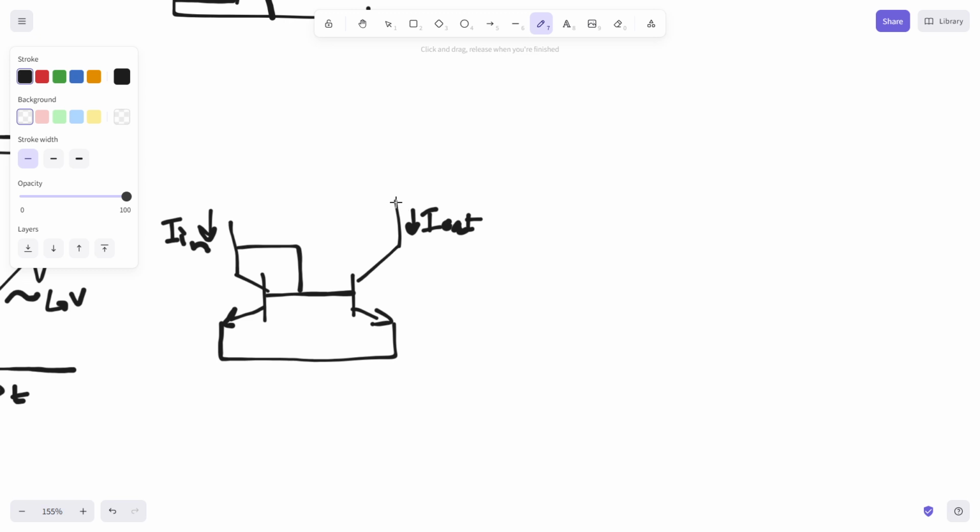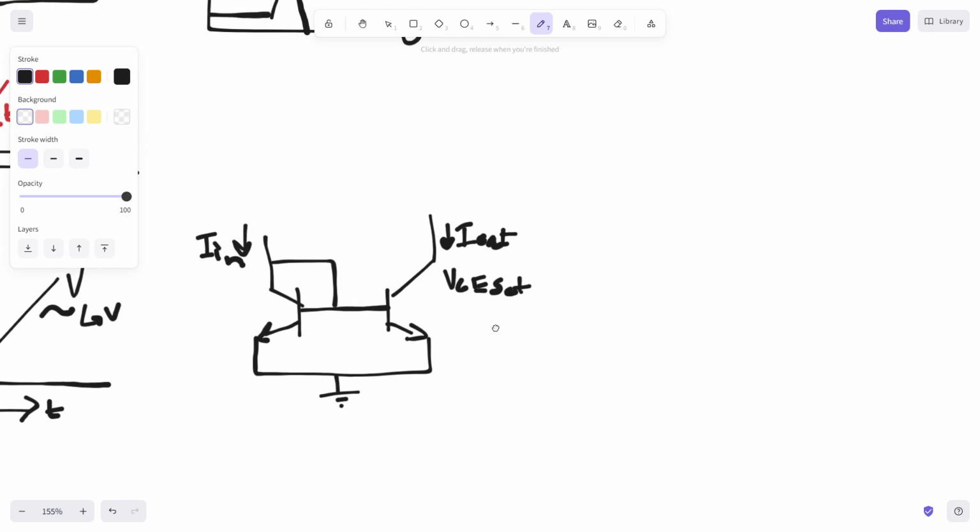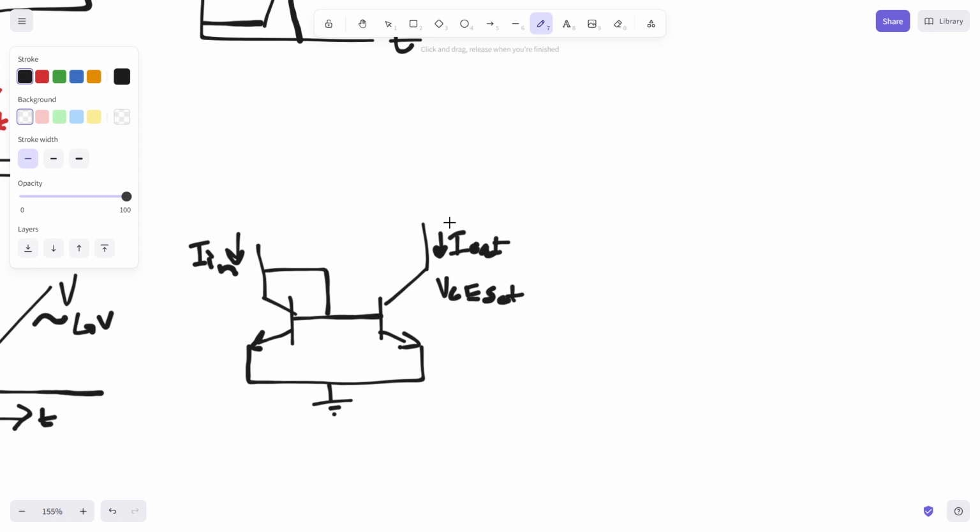Now the important thing that we go to a little further from here, we're sourcing some kind of infinite voltage through this node. In this case, this BJT will pull this node down as low as it can possibly go, which is probably going to be its VCE SAT value. It's not going to be so low, but it can get very low. If this were a perfect current source, this could easily reach negatives. If it's pulling a negative, it's sinking a current, it's going to pull this node theoretically into the negative magnitude.